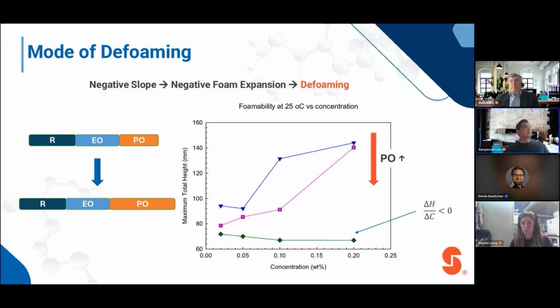If I want to reduce the anti-foam to some amount and compensate with the surfactant, you can always combine those two. That is why in many anti-foam formulations, they have an anti-foam active particle or active oil, and also an emulsifier, which is a low foam emulsifier, to cancel out that effect.